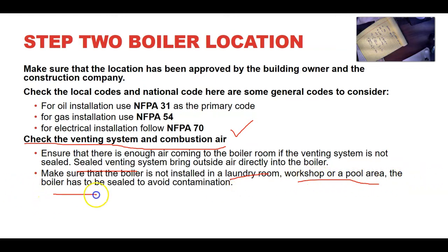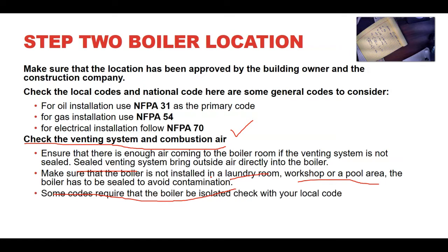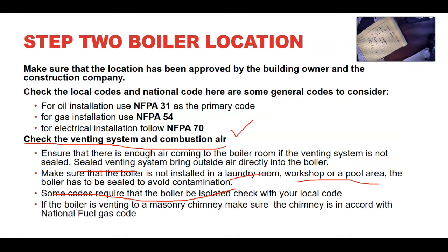And if you want to convert a basement into a living space, what's called a finished basement, make sure that you have enough air coming in, and maybe you're better off having some kind of sealed venting. Maybe it's also good to have some kind of barrier between where the people are staying and the boiler. Some codes require the boiler be installed and isolated by the local code.